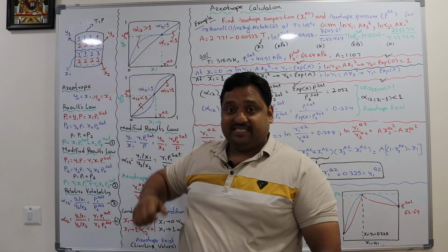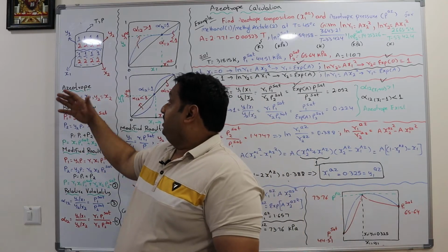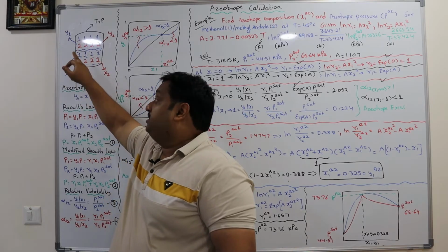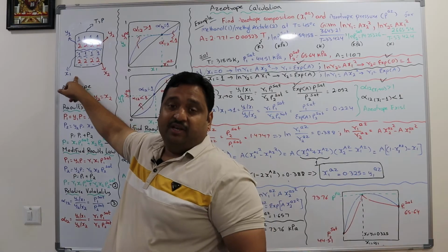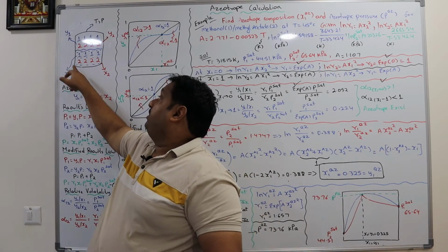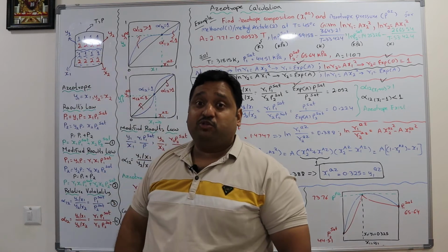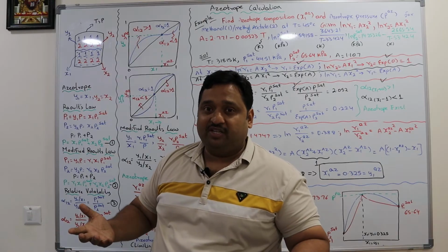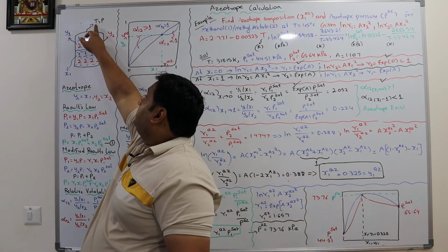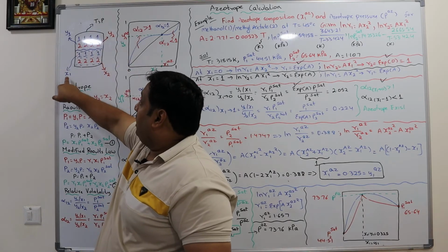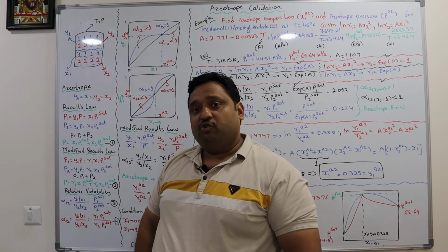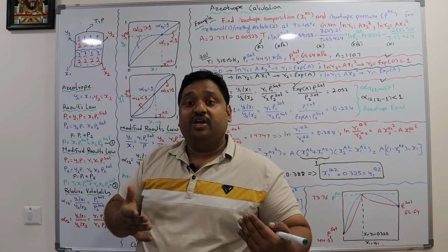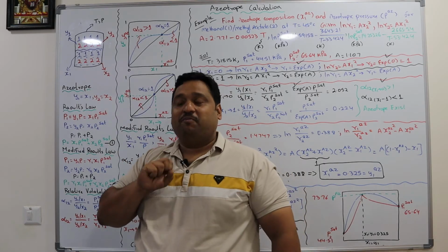So this is what we discussed in the earlier class. An azeotrope is such a mixture that even though you evaporate it, the vapor will have the same composition. That means if you have liquid of 60% composition 1, and you partially evaporate, in the vapor phase also it will be 60% of composition 1. There is no separation that is going to happen. It occurs at a certain temperature, pressure and composition. It could be X1 or Y1. Let us find out at what temperatures, pressures and compositions the azeotrope is going to form.